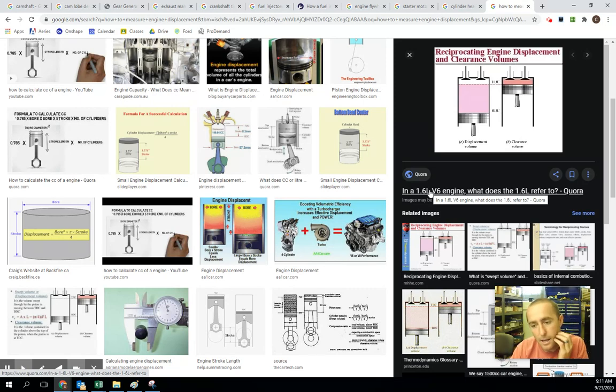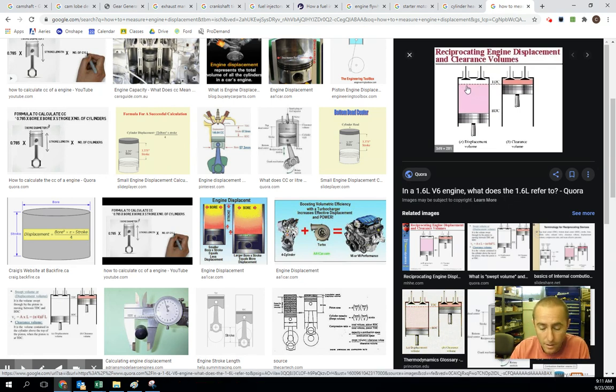All right. And so your engine size is actually the size of your cylinder. Your cylinder inside the bottom half of your engine. And how they measure that, there's a couple different ways. I've only done it with the fluid, but I bet it's probably easier to do other ways. But anyway, they measure the volume of your cylinder from top dead center to bottom dead center. All right. And so this is the volume that I bring in on my intake stroke. And so they find the diameter of this multiplied by the length of the stroke.